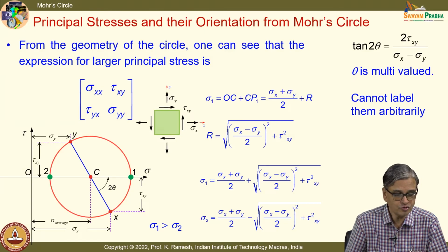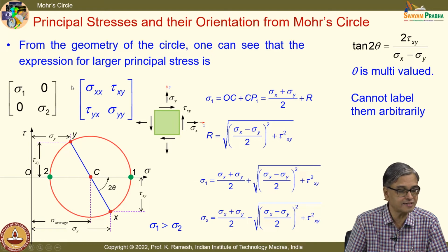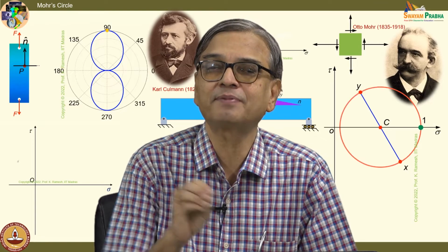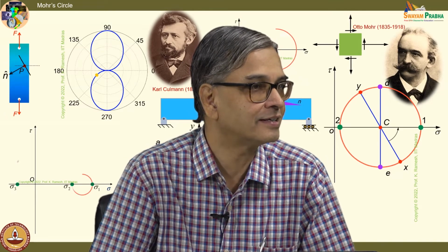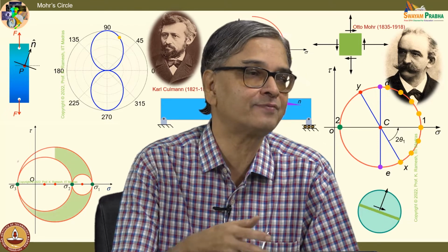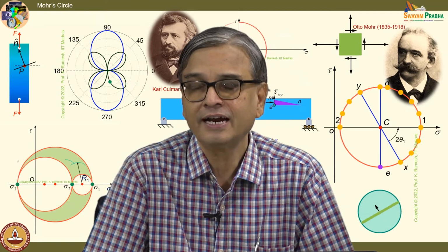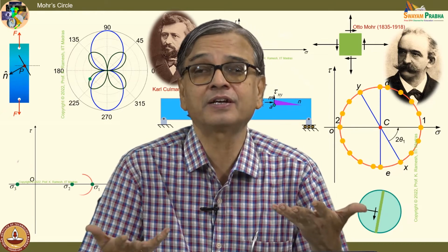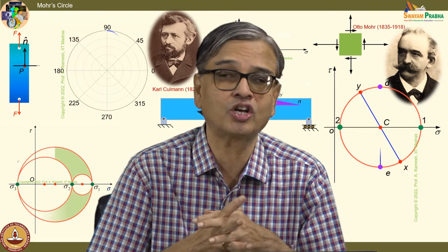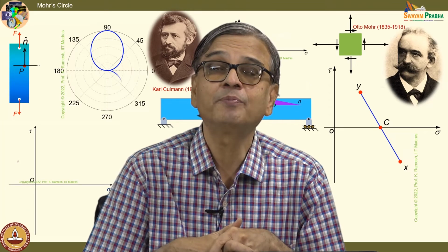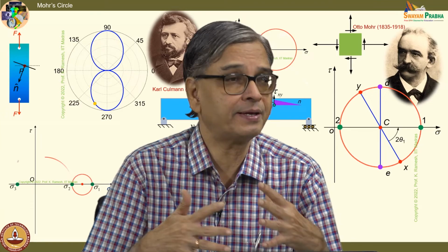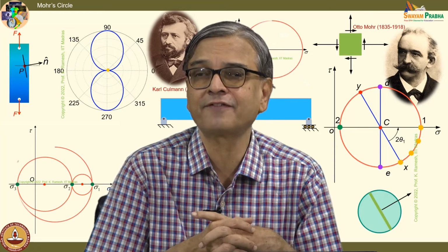Fine. So, I can also write from the understanding of the principal stresses a very simple matrix. See, if you have zeros, my multiplication becomes very simple. If I have to find out the stress vector, if I know the principal stresses, if I know the direction cosines, then I do less mathematics when I write it in principal stresses. And I have also said, when I am going to have failure theories where I have multiple combinations of tension, torsion, bending and so on and so forth, principal stresses is an easier approach to assemble all of them and then find out what is the net effect.